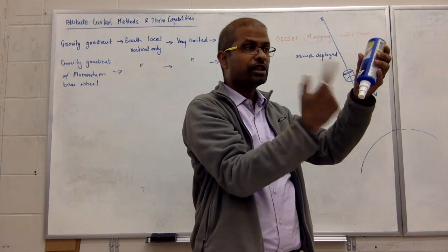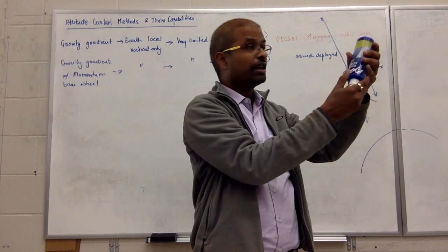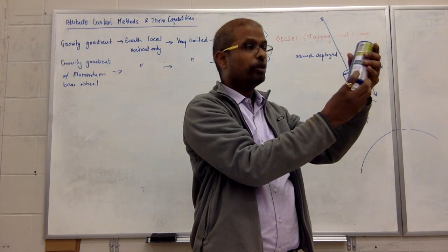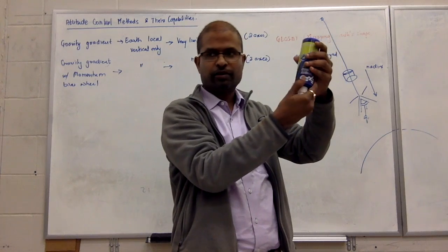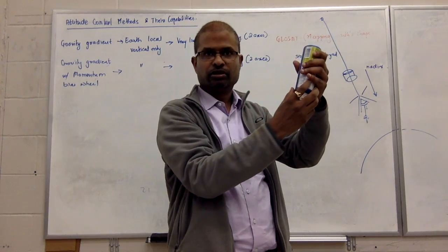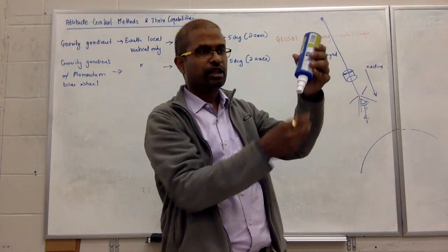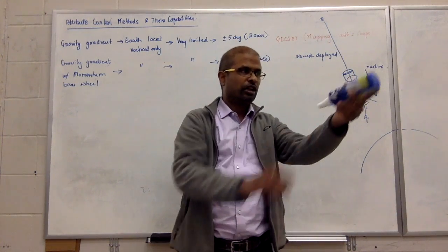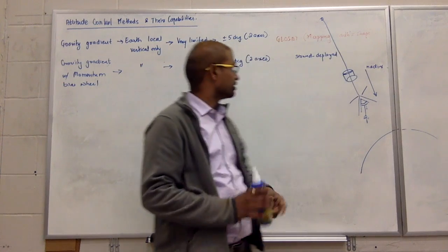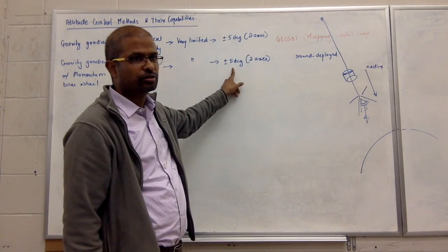If the wheel reaches a constant speed, the satellite will not spin. Only when the wheel is changing its speed will the satellite spin in the other direction. But if the wheel reaches a constant speed, the gravity gradient will maintain it like this. Now you get 3-axis stabilization, with stability of about plus or minus 5 degrees. Got it?